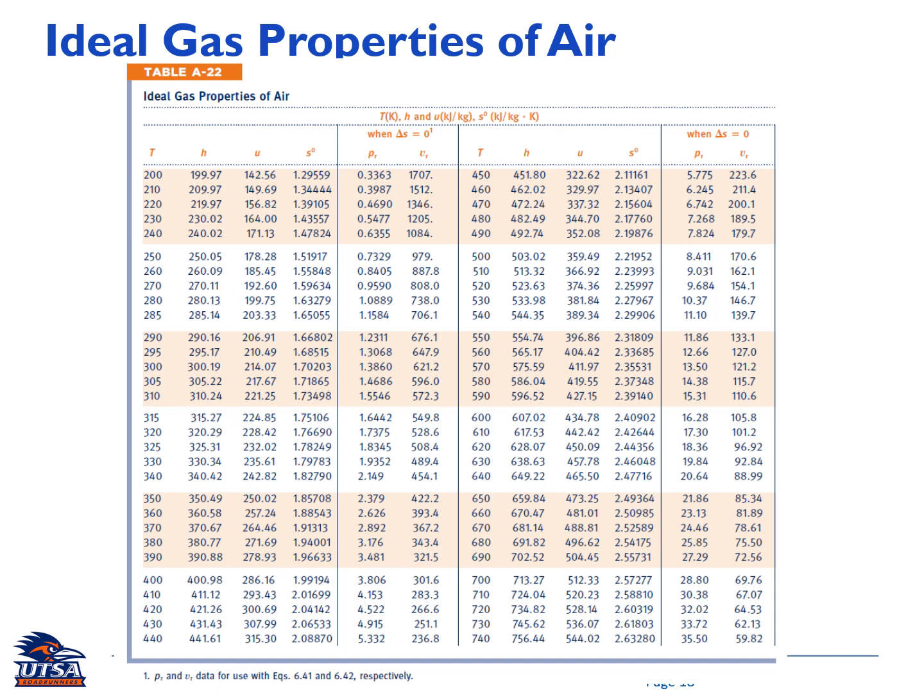On the first column, you have temperature. You only have a temperature column here. Why? Because the properties of an ideal gas, in this case air, are only a function of temperature. So the first column is temperature, then enthalpy, then specific internal energy, and next entropy. Let's hold on this one.